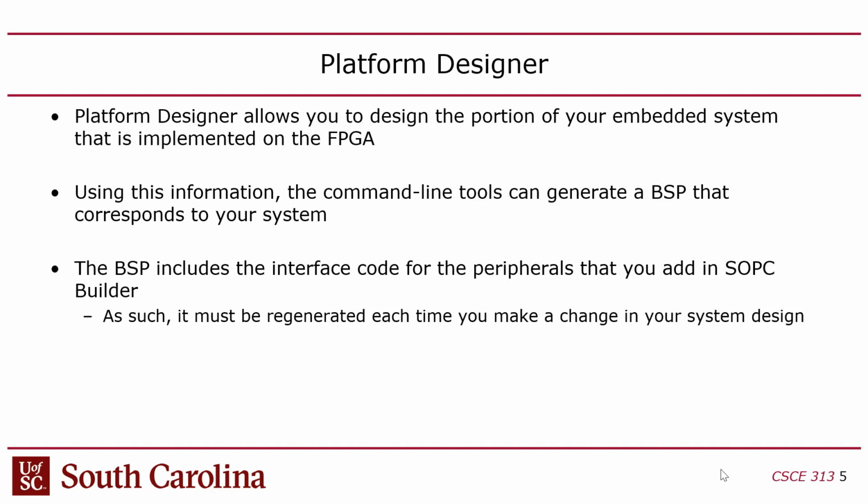Bare metal code means that you write code that runs directly on the CPU without an operating system running underneath of it. And so your code fundamentally runs in an infinite loop because if it returns, there's nothing to return to. It just crashes the system if you return from the main function.